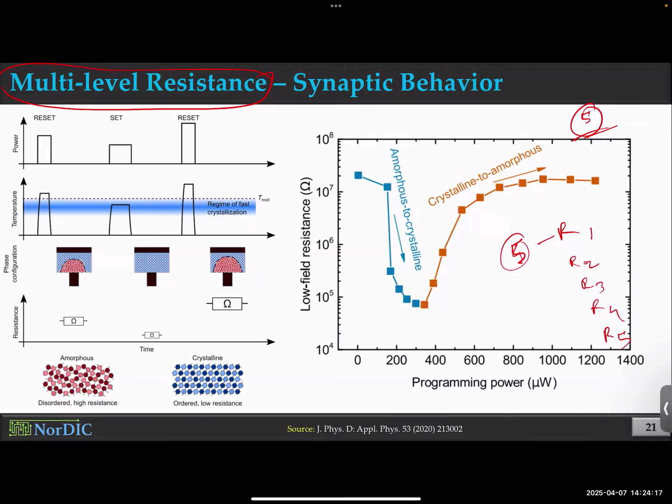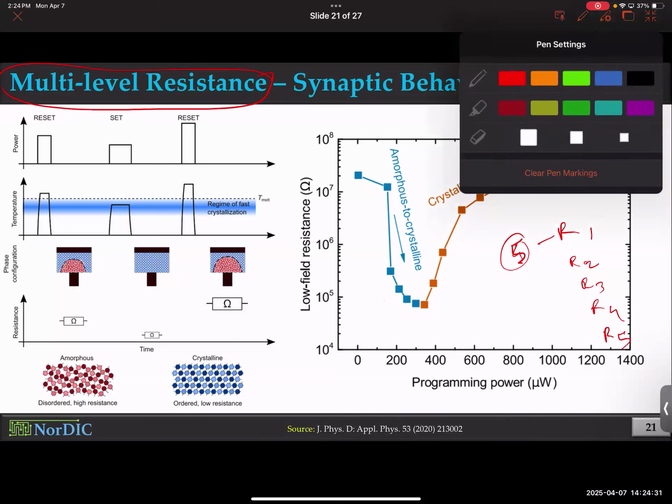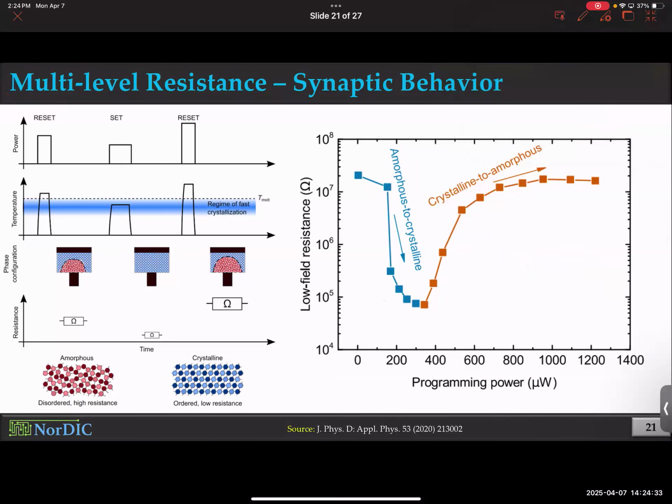Yeah, but the resolution between resistances... yes. So I'm assuming an ideal situation that resolution remains the same. Given that situation, the more levels you have, the better it is, but not just any number. You need a certain amount of threshold to cross. So at the very least, people look for 4 different levels so that they could store 2 bits at least